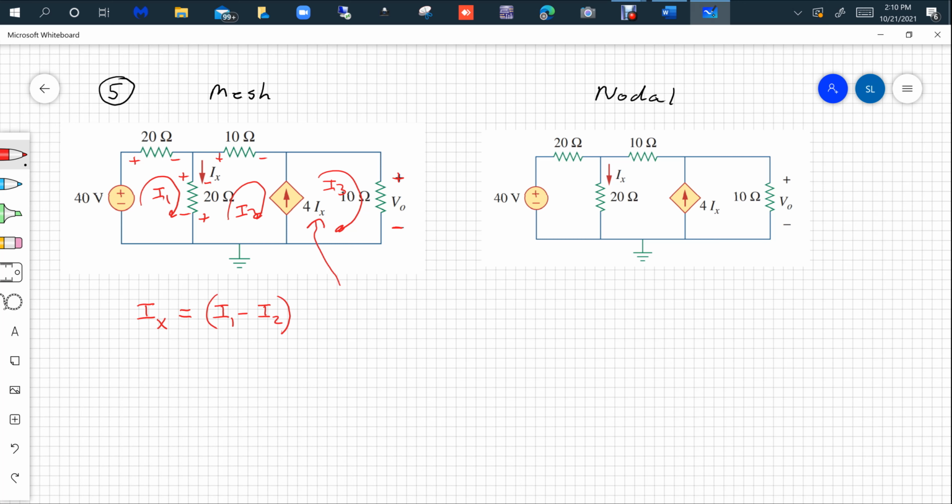If you look at nodal analysis over here on the right side, notice the direction of Ix is already given. So if you're coming up with an unknown voltage right here, V1, and with nodal analysis, that's one unknown voltage and the other unknown voltage there, you might be tempted to call it V2, but V2 would be a dummy variable, I call it. Why come up with a voltage of V2 when you know that voltage out there is V out? They give it to you here. And this is all the same point here. So don't put in what I call dummy variables. It just adds extra equations. So that's clearly V out or V naught.